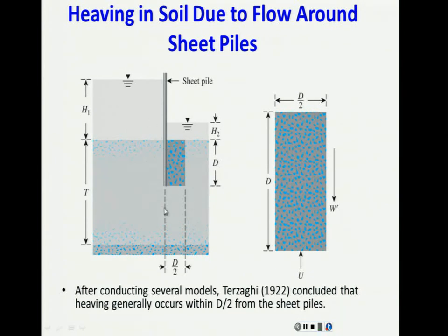If that heaving is occurring here, there's going to be some way that we can avoid that. How do you think we can avoid that? Well, actually we discussed it before, but we discussed it for washing away the fines. And the answer is we can place more weight in this part. But if I put more weight in this part, how come that is going to prevent it?